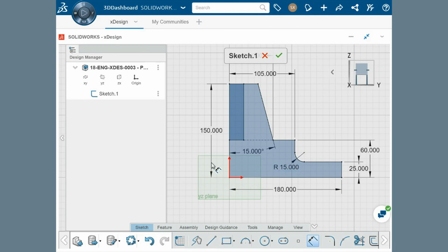Notice that all the sketch entities have changed to black, which indicates that the sketch has gone from underdefined to fully defined. This means that the sizes and relationships of all the sketch entities are set in place. They were also all created using the same dimension command. However, I do want to add one more sketch entity to show you how to add a diameter dimension.